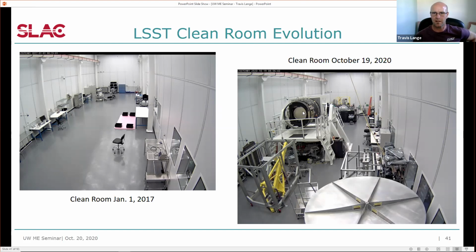So we can rotate this thing so that it points down, and we'll do that for the final testing. Once it's completely assembled with the big lens on there, we'll take these deck plates out from the stand, rotate the camera, and face it down. We'll enclose it in a dark box and put some light projectors inside that dark box to test this thing at the completed camera assembly level.